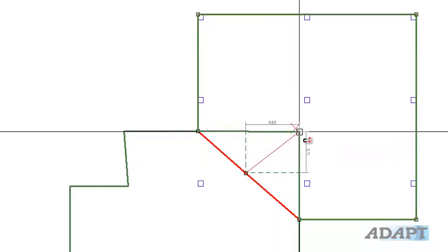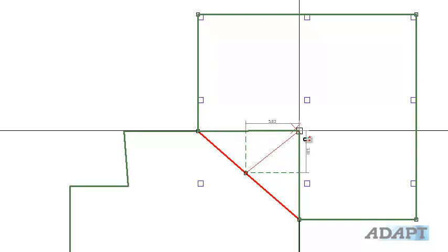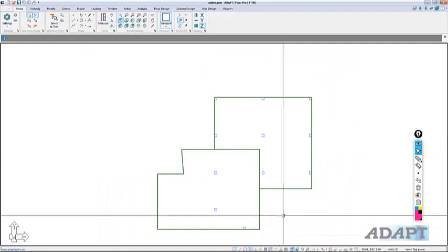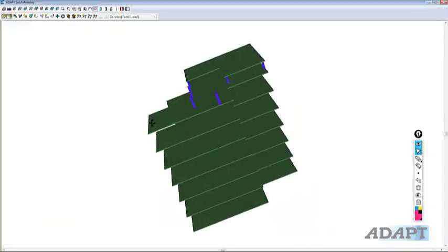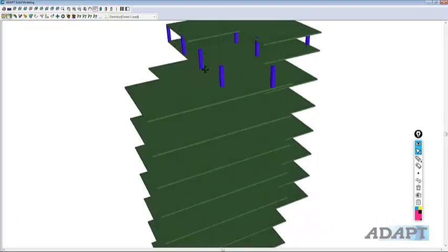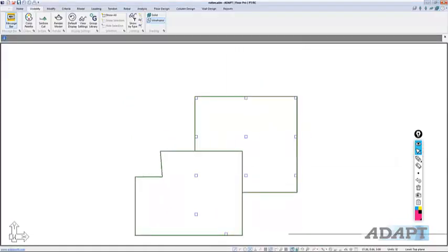Okay, I'll escape so I have an extra point and I can move that point. And I can move it if I know the dimensions. I could eyeball it, if you will, by just using my cursor lines to align it. Or I could use, again, the line tools to align that. Now what I have, if we go to Visibility under the Render Model tool, you can see I have something that looks like this. And I have 3 columns here I actually want to delete out of there also. Okay, so let's delete those.